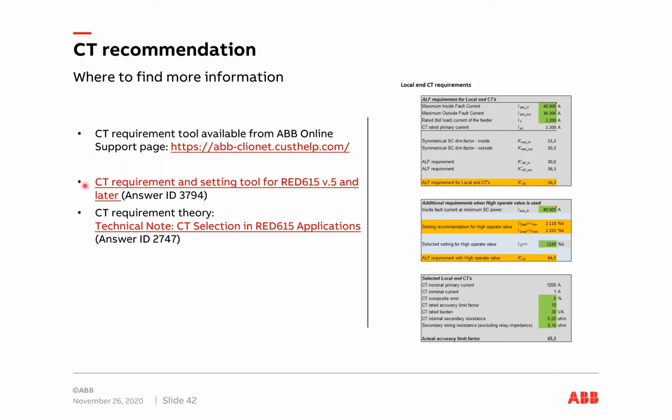This Excel tool will help you calculate the settings for the differential characteristic, and it will also help you check the CT requirements, so it will fulfill your application with its short circuit currents.